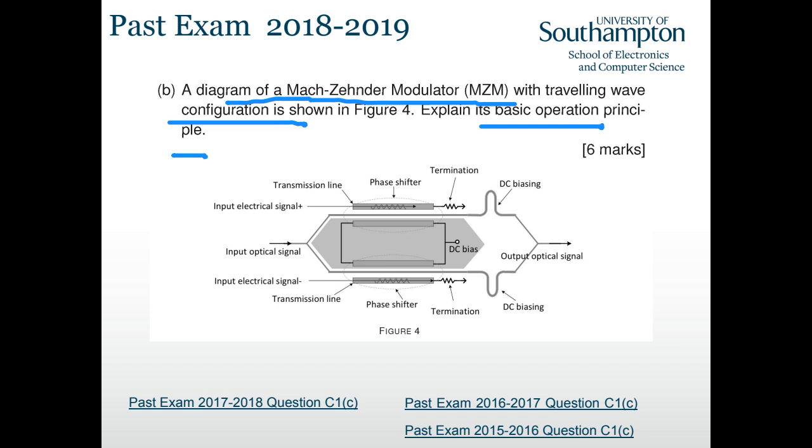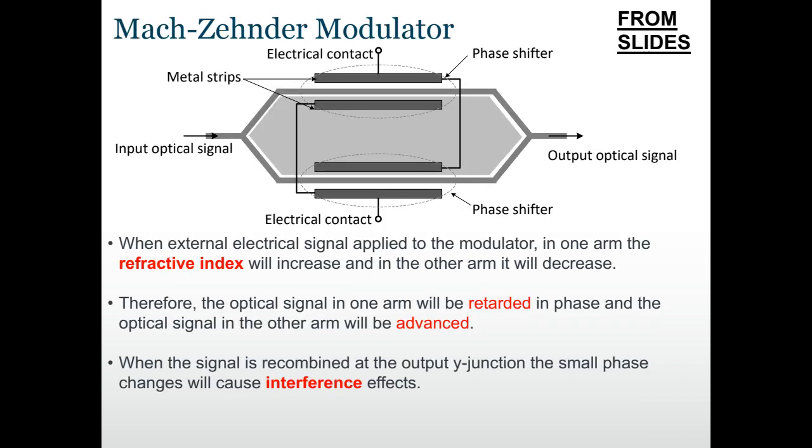The expectation on the first level is that we have 2 arms, and optical signals travel on the 2 arms. We want to change the speed of the two optical signals so that when they combine together, they can interfere either constructively or destructively. This gives us the degree of freedom to modulate the optical signal.